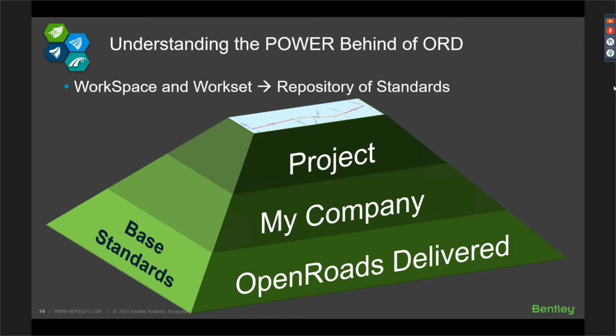You have the ability to utilize the predefined country or regional data set that comes out of the box upon installing ORD, or use this as a basis of customizing your organization or even your project configuration. So these workspaces are a repository of all standards that you may have in your project. It stores all your default CAD and, of course, civil design libraries, including your annotations, civil object styles, like your alignment styles, geometry styles, terrain styles, corridor styles, and, of course, your drawing sheet styles. When I say drawing sheet, these are your plan, profile, or cross sections.